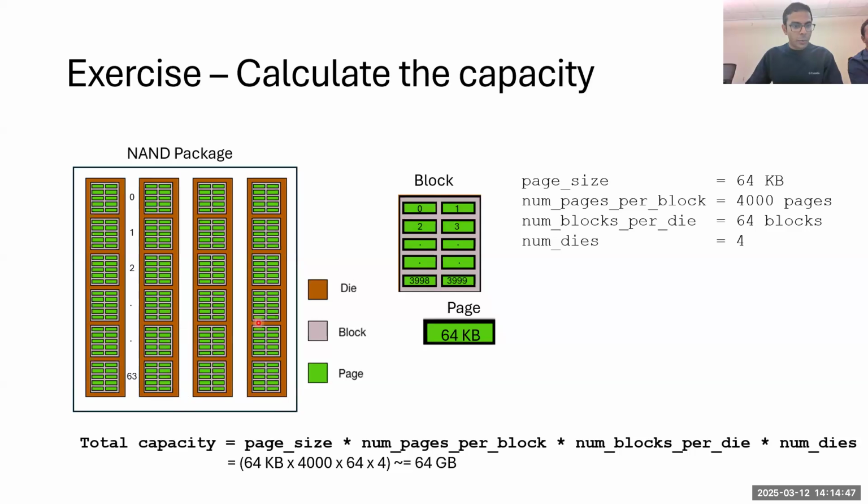Let me repeat the question for everybody. So the answer is yes, we can. The only requirement is we can write one page at a time, not less. And definitely we can hold more data and write one page at a time, 2, 3, how much ever we want. And as we'll see in the upcoming slides, SSDs themselves have a DRAM in them, and we can hold data on them for optimal placement if we want to. Like we can accumulate more pages before we write to NAND.